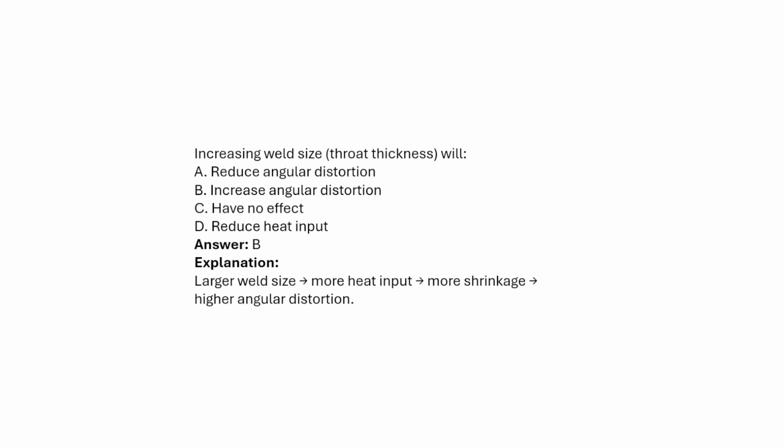Increase in the weld size will reduce the angular distortion, increase the angular distortion, have no effect, or reduce the heat input. The answer will be B, increase the angular distortion.